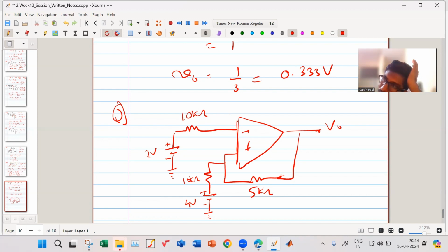I have done some Sallen-Key low pass filter long ago. In that, it had a combination of both negative feedback and positive feedback, and because of that it is only stable under some particular condition. So that's why I cannot tell this one. What I'll advise is you can simulate it and check, then you can be sure whether you can apply the virtual short concept or not.